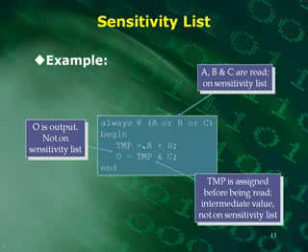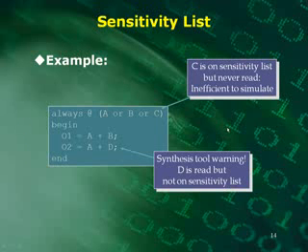And temp, because temp is assigned before we actually read it right here, it's an intermediate value, so it doesn't have to be on the sensitivity list either in this case. So I like the newer notation. You just put @ star, and you don't have to put any of this mess. My personal preference. But I'm going to show you this in case you ever run into a problem and you have to list them for some reason.